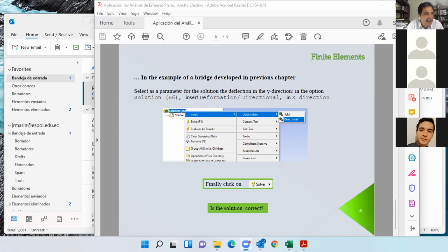Oh, that's fine. What about the sign of the displacement? Yeah, the sign is correct. How do you know? Because it showed me the deformation. Yeah, but in what direction? Downwards. Yeah, that's the answer. Okay, so remember, you get the solution, but you have to ask yourself, does that make any sense? At least you have to check the sign of the deflections. Sometimes a 3D structure can play tricks on you. But in general, at least we have to check the direction.